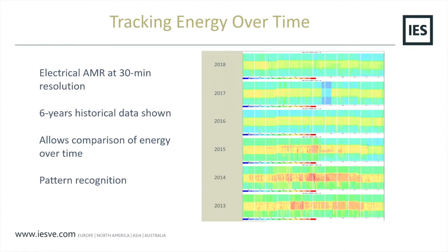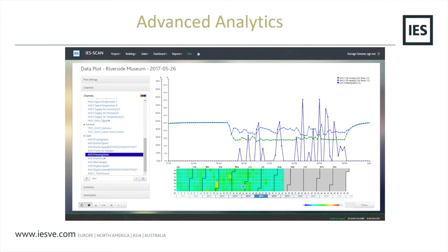So you need to get access to the data, address some of the previous challenges, and then when you've addressed those, you get your data coming. Then you can start to get into the analytics, the visualization side. Just a bit more detail. This is maybe how it looks for my guys, a bit more advanced. We're looking at 2 or 3 BMS points, and we can identify issues with this, maybe a heating valve running when it shouldn't be, but that's more advanced analytics.